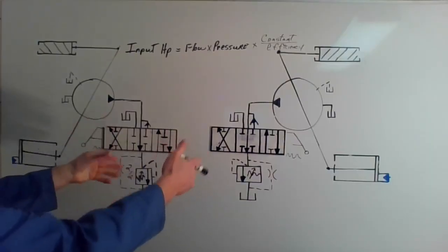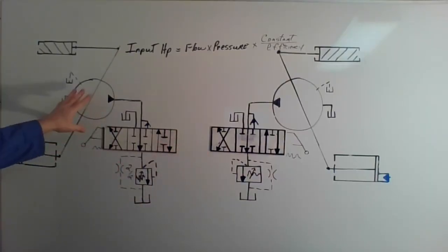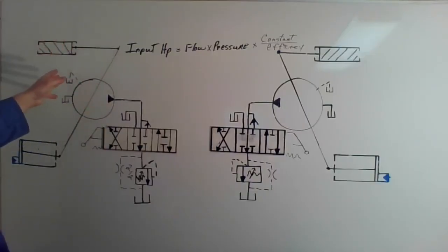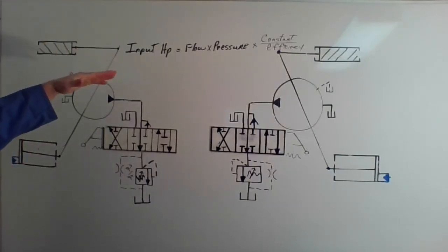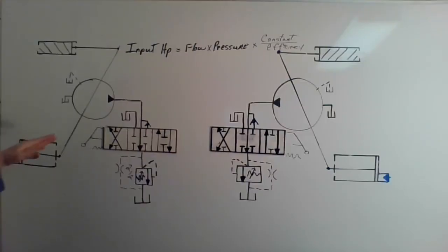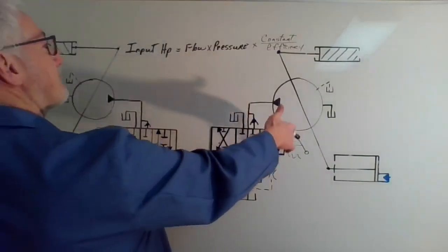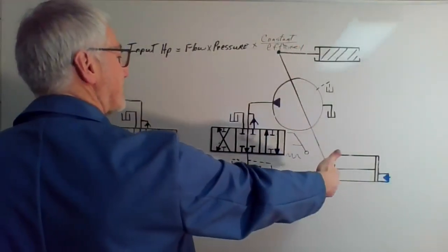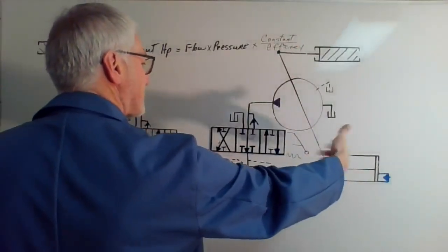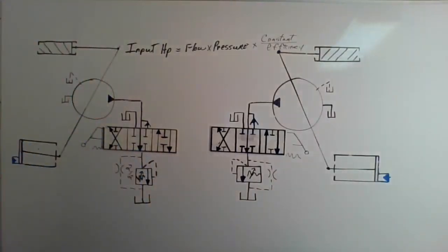So there'll be separate valve banks for this. But what I have is a variable displacement pump, a bias spring, and a stroking or servo piston over here, which will work against the bias spring always trying to upstroke, and then hydraulically we're going to try and de-stroke under the right conditions. And I have exactly the same thing over here. Another variable displacement pump, another bias spring, and another stroking piston.